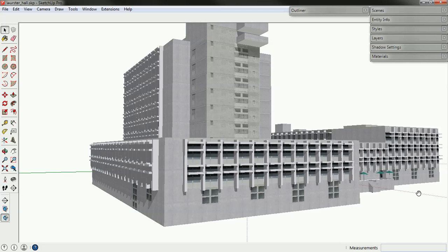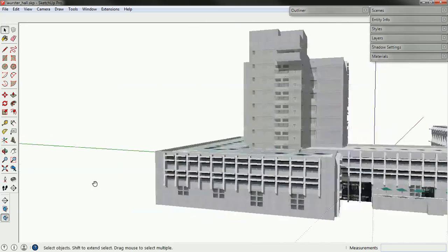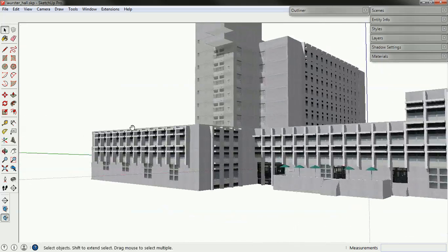And into that air, there are different thermal fluxes or differences, such as sun or cold or internal heat. And so what you're essentially doing in the thermal model is heating up and cooling down that volume of air. So there's a very different approach to modeling that than there would be to modeling a three-dimensional architectural building.